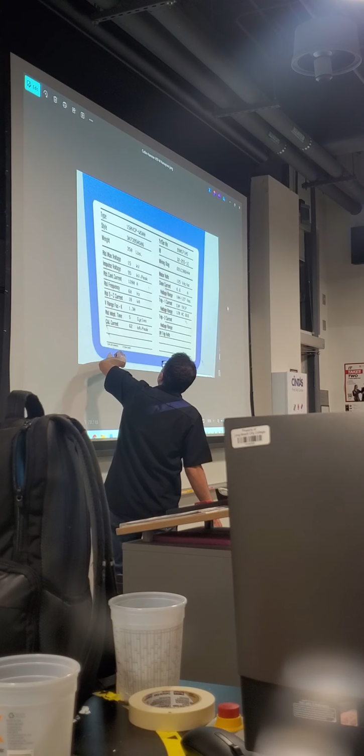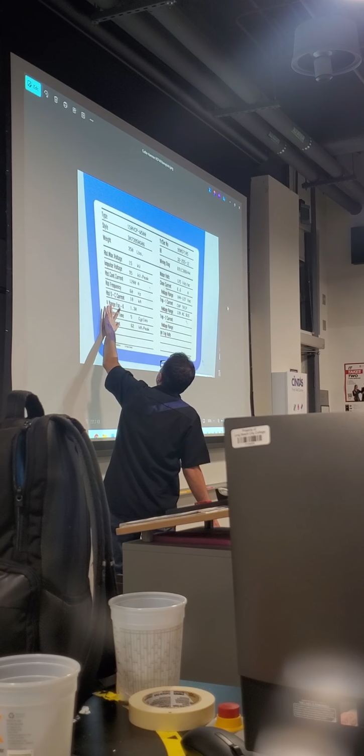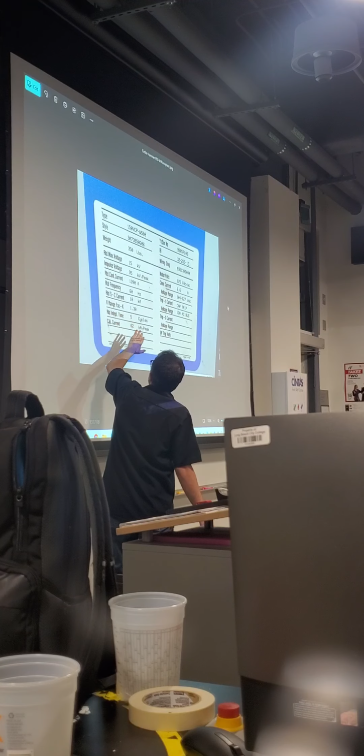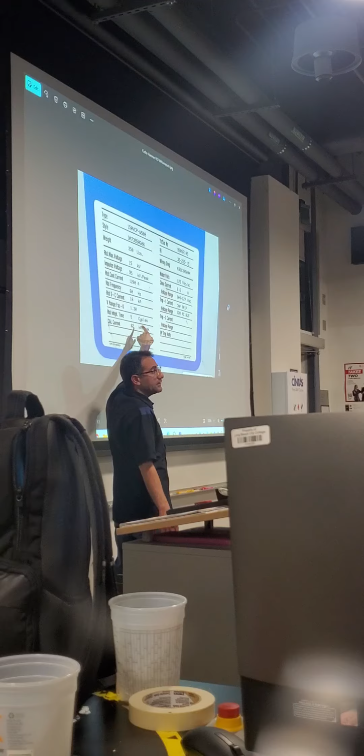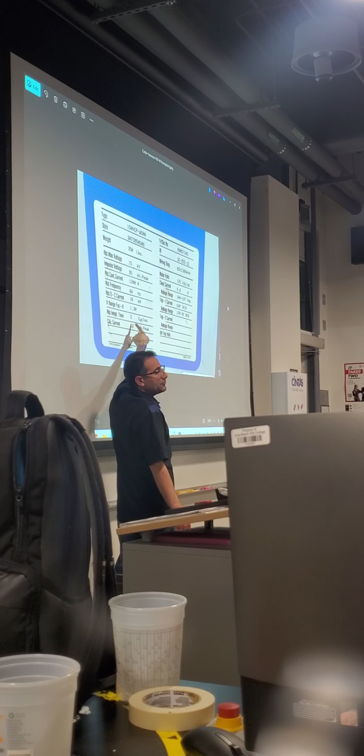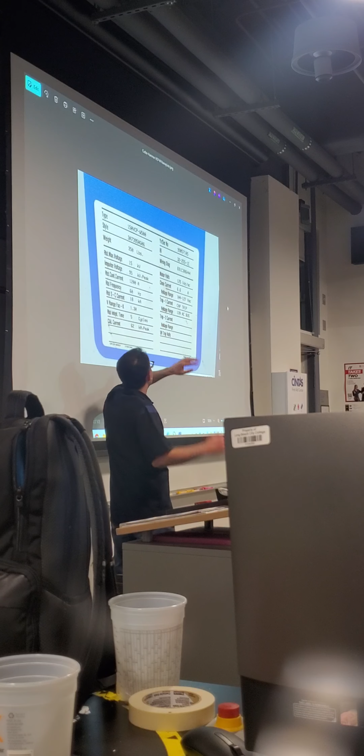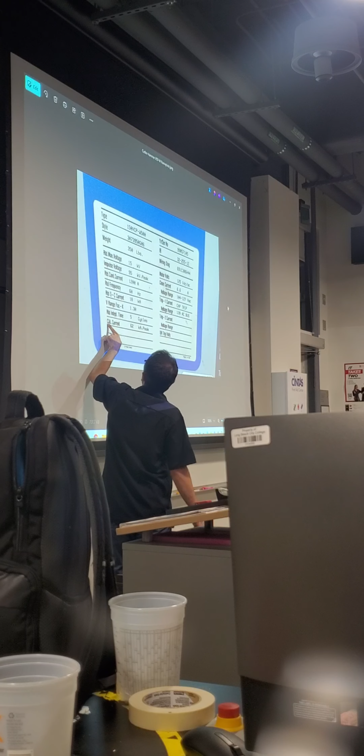Let's see what else we have here. The K factor for the voltage is 1.3, that's for asymmetrical, rated interrupting time 5 cycles. So maximum it takes 5 cycles to clear the fault.